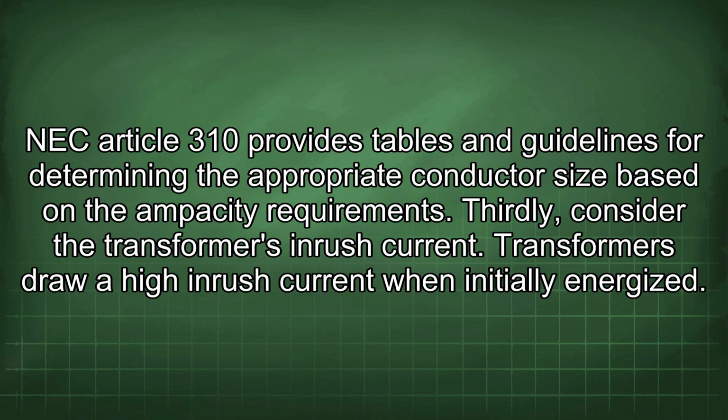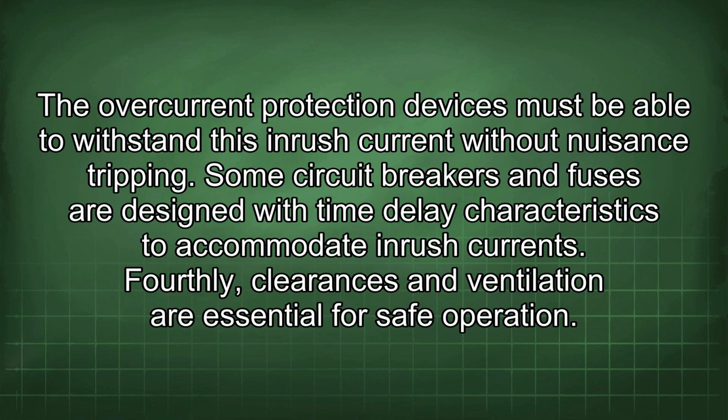Thirdly, consider the transformer's inrush current. Transformers draw a high inrush current when initially energized. The overcurrent protection devices must be able to withstand this inrush current without nuisance tripping. Some circuit breakers and fuses are designed with time delay characteristics to accommodate inrush currents.